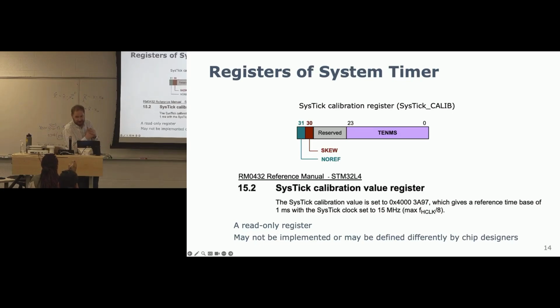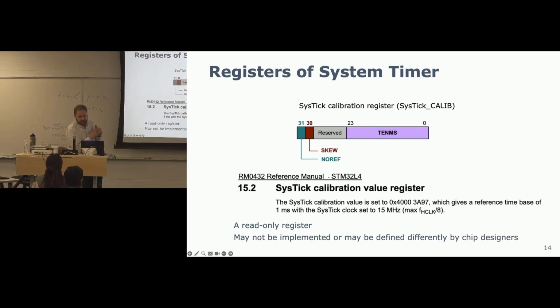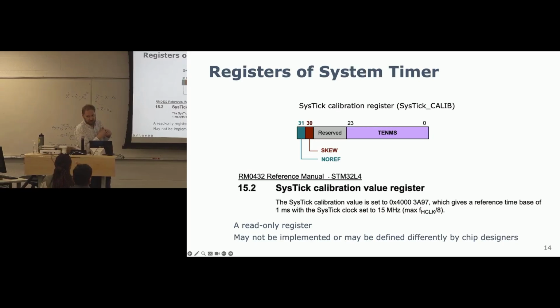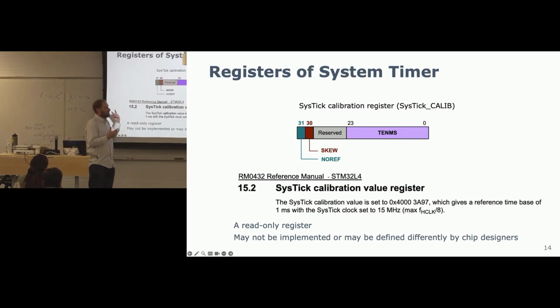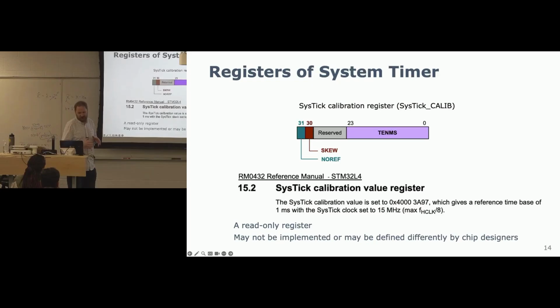So this is all to make sure that when running a particular task or program that it's within a certain time, so that it moves on to the next task. This is to ensure that, yeah, okay, you can say it that way. So the goal of this module is to ensure that you have some way to set priorities for tasks and to ensure that you transition from one task to another task without necessarily worrying about did the task complete. So you set up a timing schedule and you say, okay, that task is done. You do a context switch to another task.